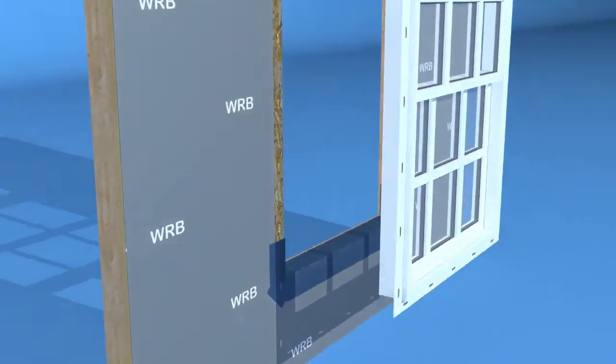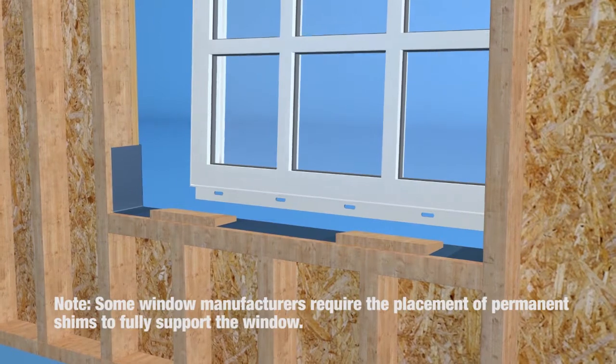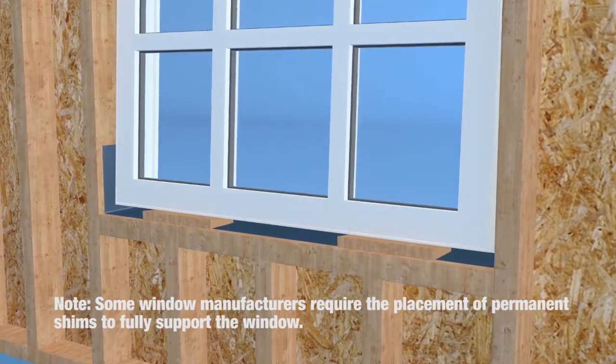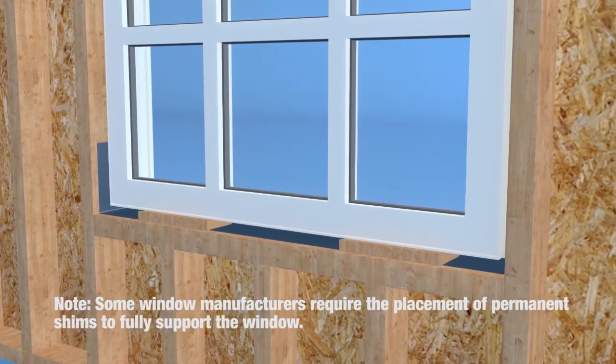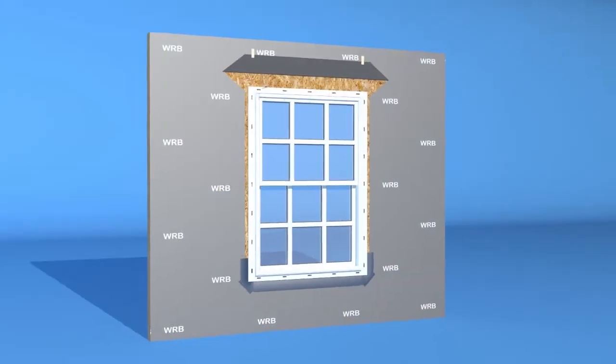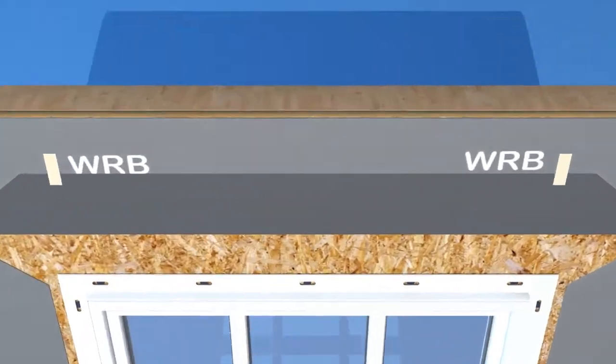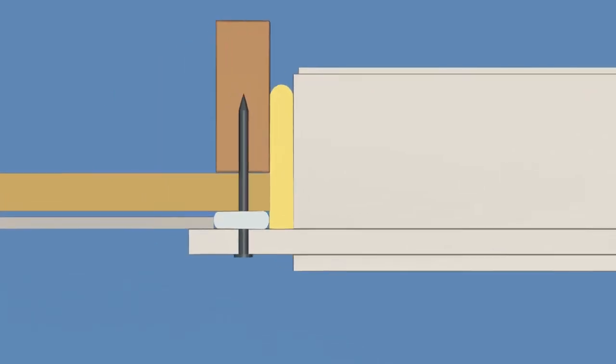To ensure proper installation, it is recommended to place temporary shims at the sill during the installation of fasteners to facilitate leaving the recommended minimum 1/4 inch gap at the sill. Applying sealant near or over the nailing slots on the window flange ensures the holes created in the sheathing by the mechanical fasteners are sealed.